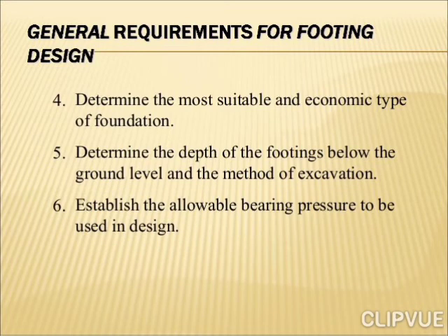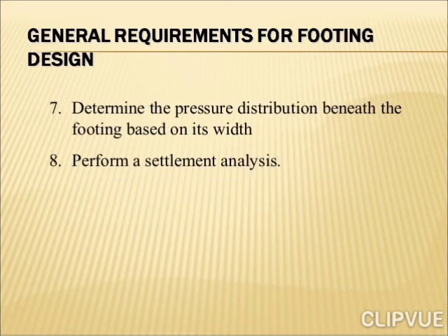Determine the most suitable and economic type of foundation. Determine the depth of the footings below the ground level and the method of excavation. Establish the allowable bearing pressure to be used in the design. Determine the pressure distribution beneath the footing based on its width. Perform a settlement analysis.